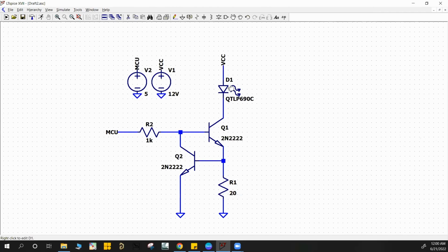And again, as I said in my first episode, for this LED to actually work, we need to make sure that we're at least at 5 volts. Again, this is a simulation; it works with 5 volts, so this VCC has to be at least 5 volts. But in real life, it's best to keep it at 5.1 or 5.2 volts, just to ensure that the variation between different LEDs, which we call LED binning, won't really affect the performance of the LED. So now that we have this, the circuit is done.